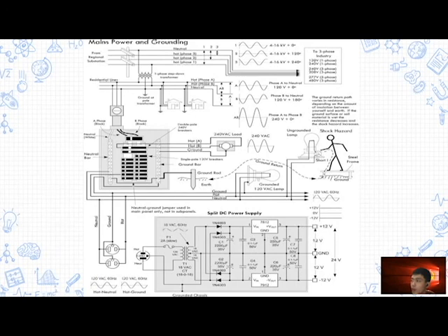The ground wire, green colored or bare, is connected to the ground bar. Then run the cable to where the 240 volt load is located and attach the wires to the corresponding terminals of the load.